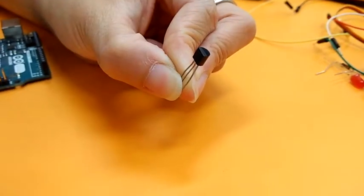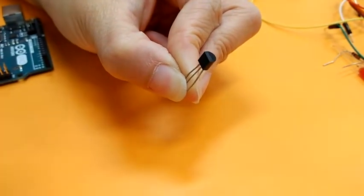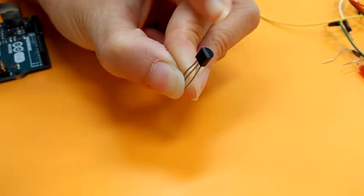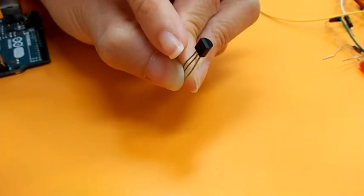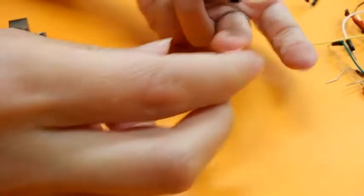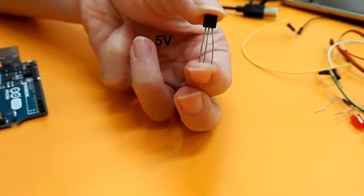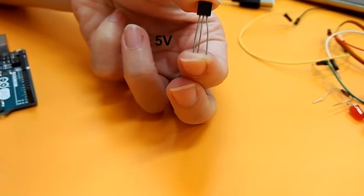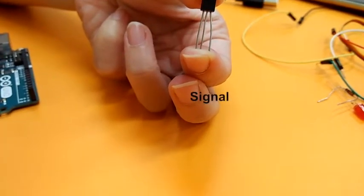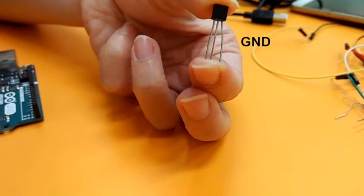First, let's take a look at our temperature sensor. The temperature sensor has 3 legs, and it has a curved side and a flat side over here. So, with the flat side facing you, the far left leg is 5 volts, the middle leg is signal, and the far right leg is ground.